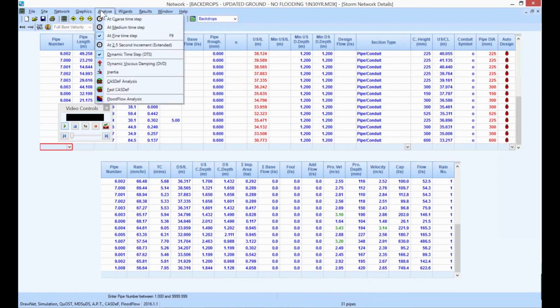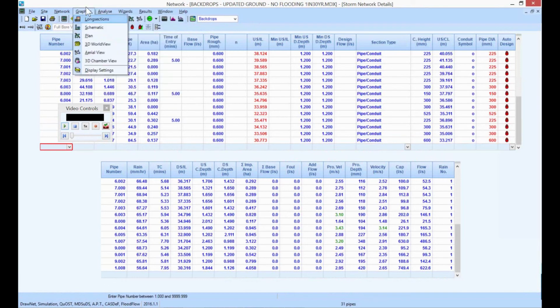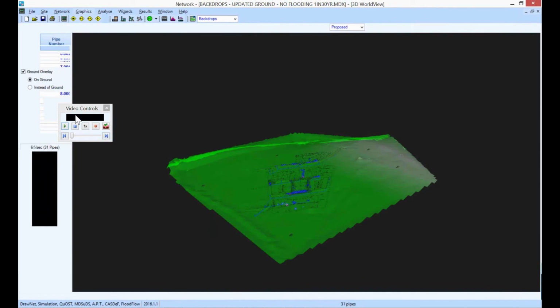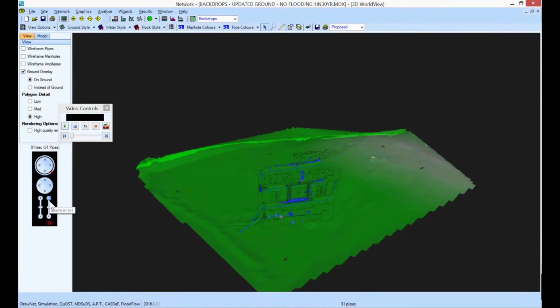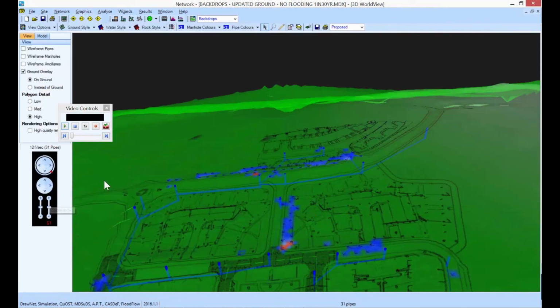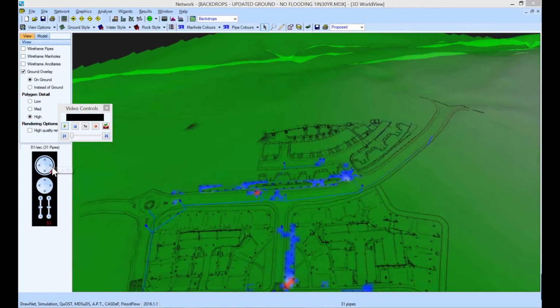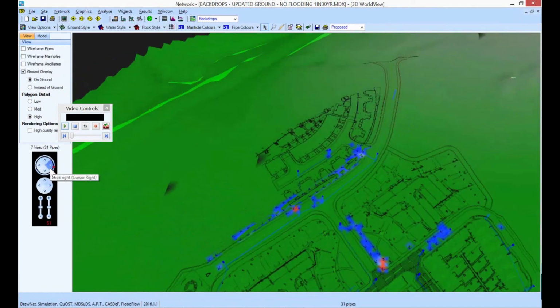and because I've used a flood flow analysis, I've combined the 2D overland flow routing with the 1D network, and now I can have a look at these results in 3D and have a look at exactly what's going on. So what I want to do is look at that road that Dan had specifically told me about. He was looking at the channeling on. So we can have a look at this road here. And if I play through the results now, what you'll see is that the 1D network starts to cope with the flows, and then eventually we start to suffer from some flooding.